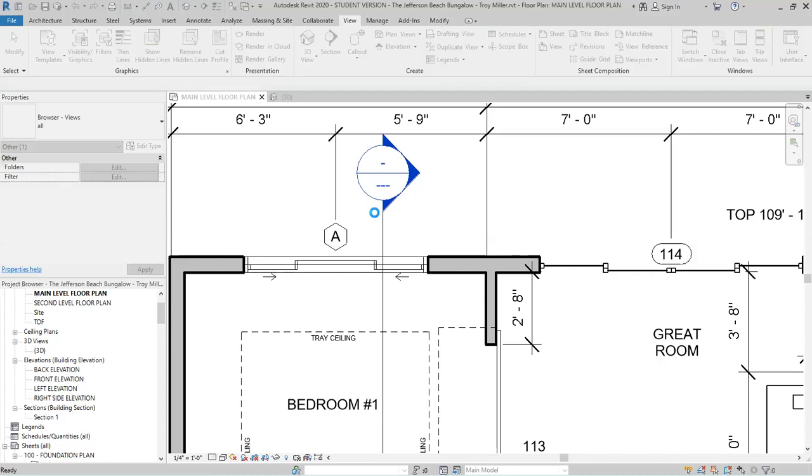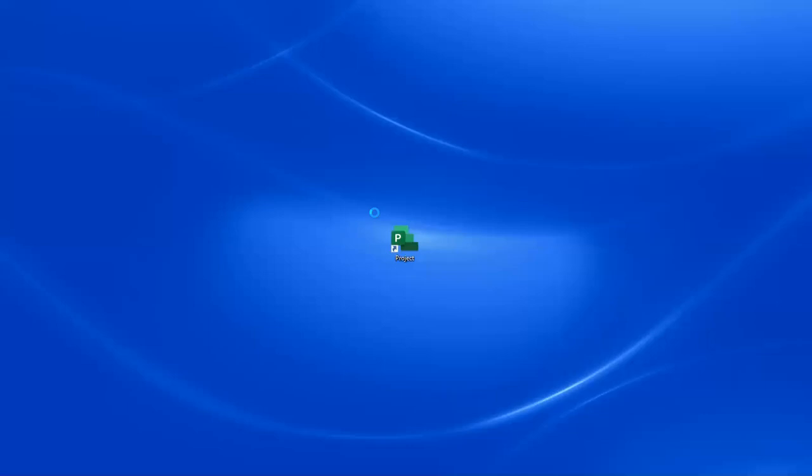after this saves, because it saved once, because I double clicked on it, it will actually take me to the view that this section's creating. So this is a vertical cutting plane. And as soon as this view is created, what we'll be looking at is the wall through the door to whatever distance has been defined.